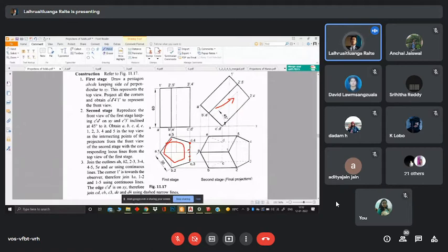It's going to stay there. So that is why we are making that particular edge perpendicular to the vertical plane, like this, because we are going to tilt it in this direction at 45 degrees. So we make sure that that particular edge remains the same. So we make it perpendicular to the VP.